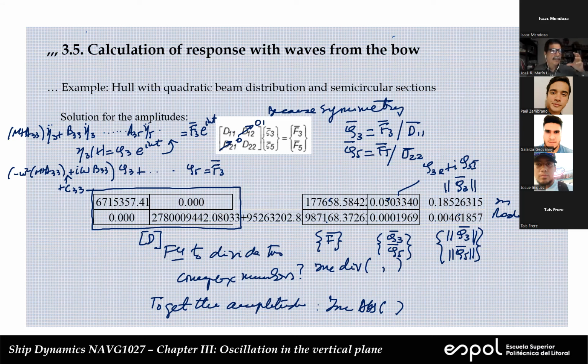Basically what you are doing is comparing your results against some reference values. It's always a good idea. It's like a mechanical way: you calculate something and you compare it with, for example, at least look at the ship which is on your side. Basically, that's what you have to do all the time. So you calculate the thickness, and see what thickness do you have there, to see if that makes sense or not. These procedures are so long, and there is so much data you have to consider, that it is quite easy to make a mistake. So please try to implement that.